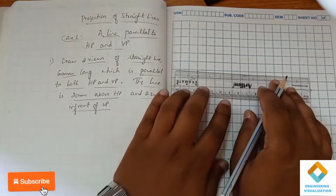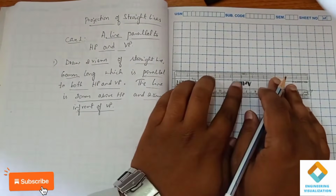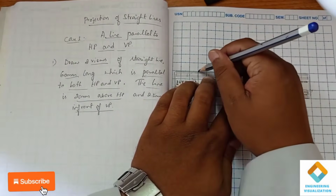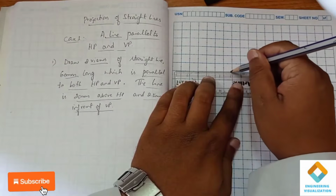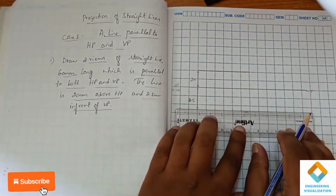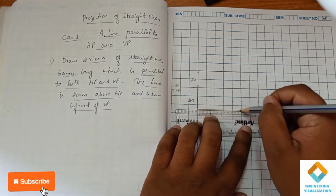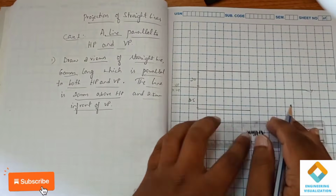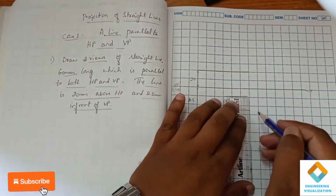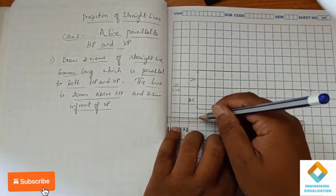So here we have to draw a line of length 60. It is parallel, which means we have to draw a straight line. From this end we can take 6 boxes, up to 6 boxes here, and here also we have to draw 6 boxes. So this is our line and we can show the dimensions. This is our top view, which is also 60 mm.